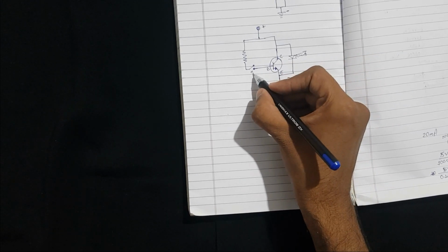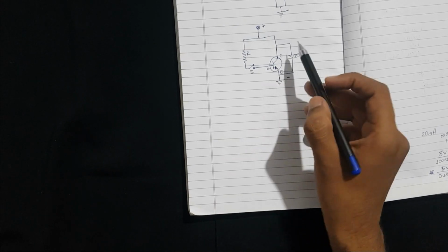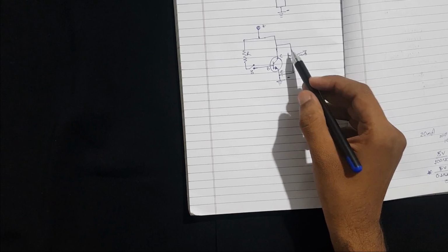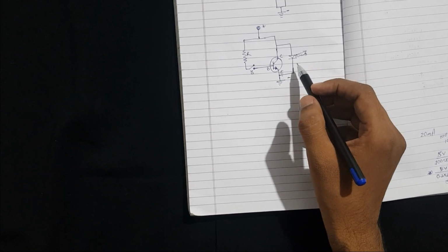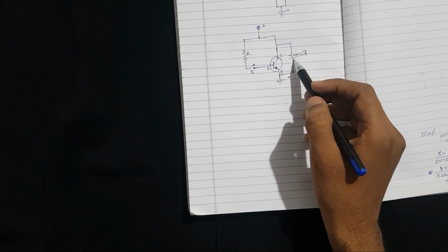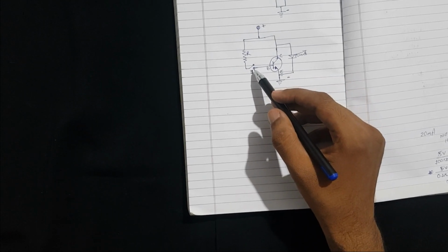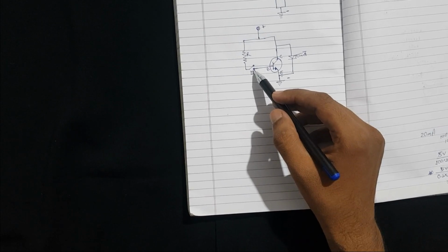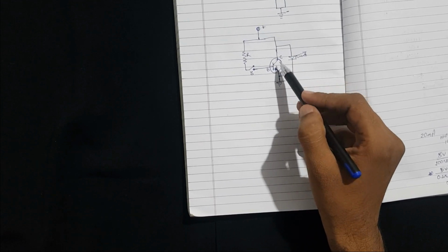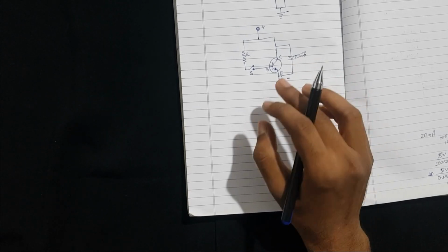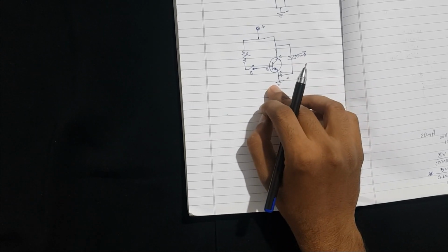So what will happen is that when we press this key, this transistor will turn off, so there will be no potential difference across the terminal of this LED. So it will turn off, and when we take our hands off from the switch, it will be open, so there will be a potential difference across the terminal of LED. This is the diagram.